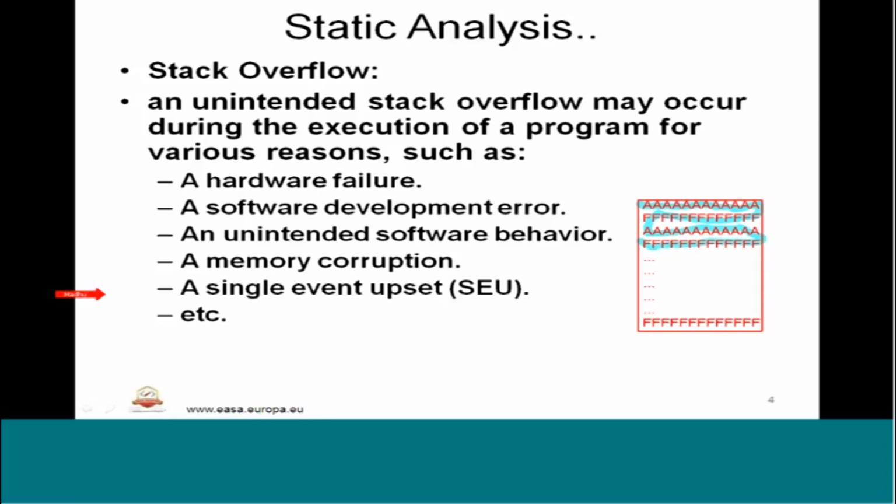We know that the program that we have tested has utilized this much stack. It means this much is still reserved. So we read this portion. We know that a definite pattern is there, and we are able to read it. We know that that portion of the stack is not overwritten by the stack data. So we know that there is still space available in the stack, and the stack has not overflown, or we know how much stack is used. So based on that, analysis can be done.